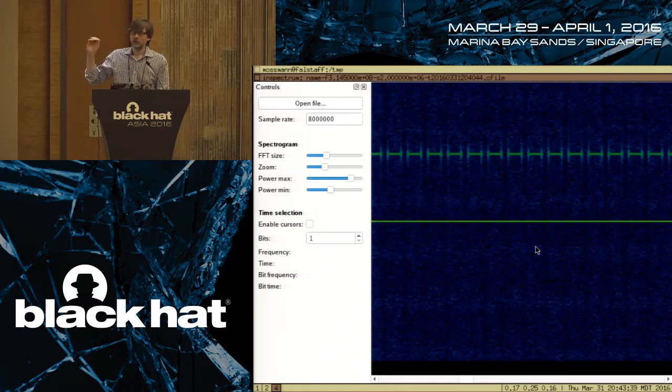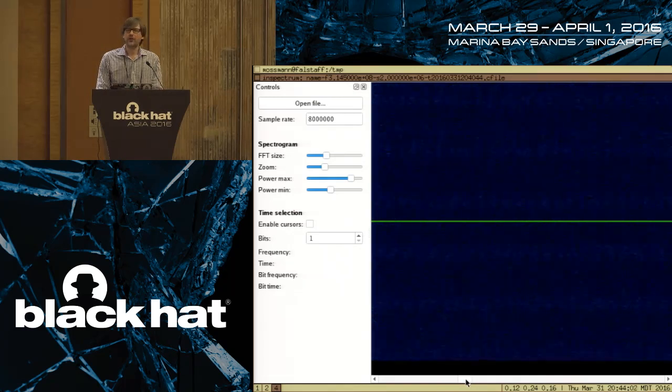And the color goes from this blue background color to this green color when there's an active signal. It abruptly turns on and off. So this modulation I can easily identify visually as being on-off keying, which is the extreme form of AM. It's turning the amplitude of the radio transmitter on or off.